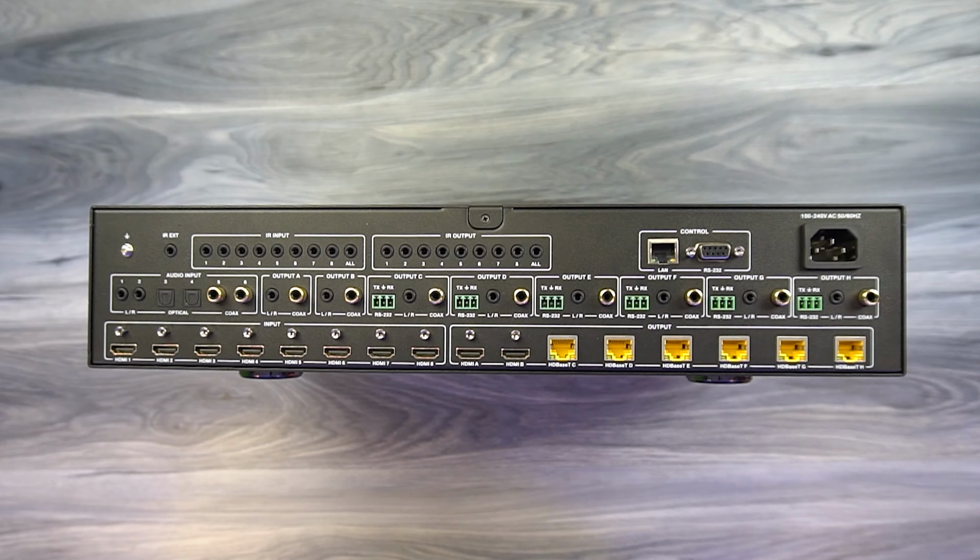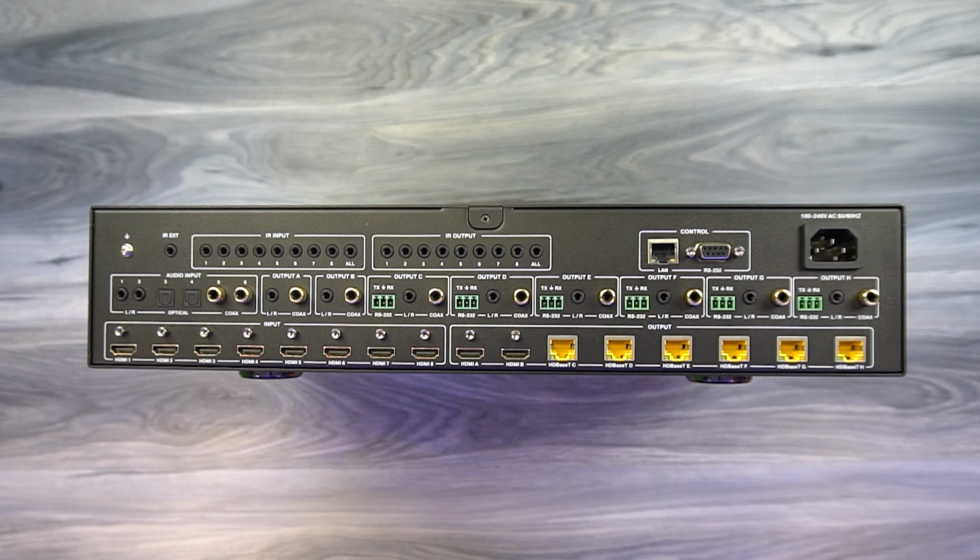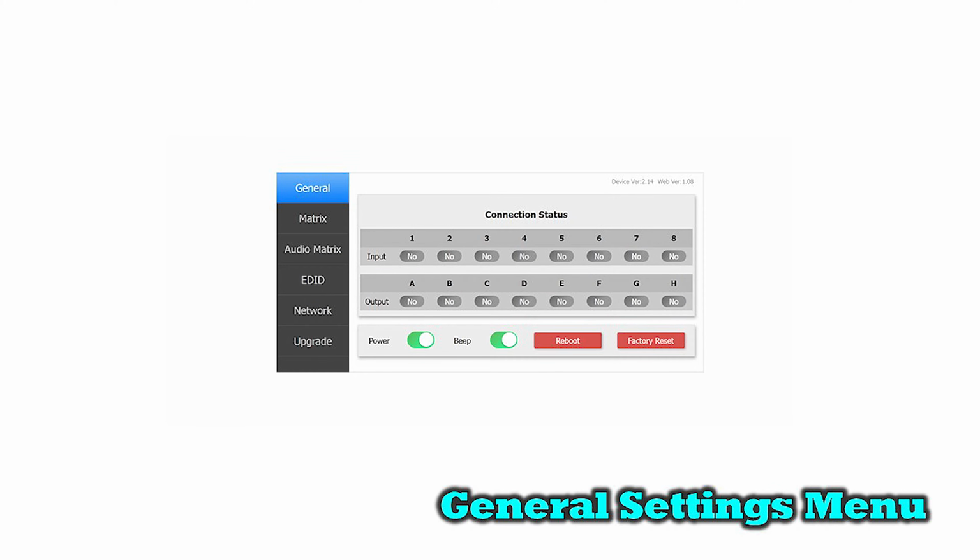Once you've made that connection, simply open a browser and type 192.168.1.100 into the address bar and hit return, and that will open up the graphical user interface that allows you to make any changes needed to the configuration. When you first connect to the Matrix, you'll start on the General tab that provides a lot of good information on the current status of the Matrix.